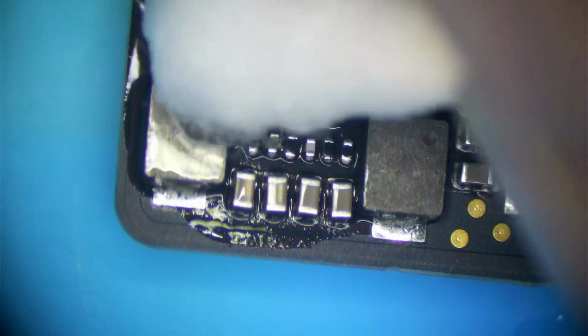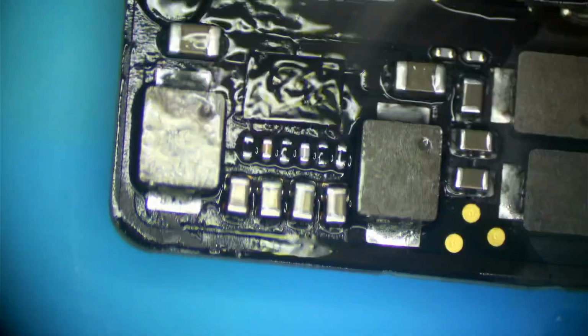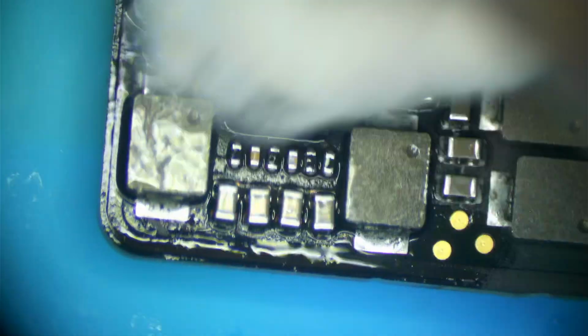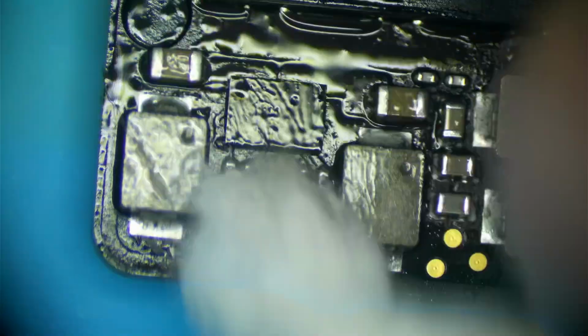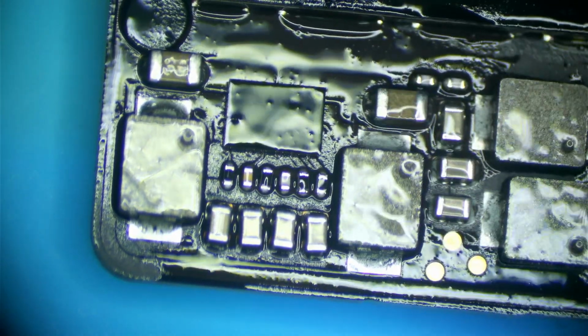As far as these go, I think what we're actually going to start doing is conformal coating these areas on devices that come in, because this is risky just leaving it. It is very concerning that Apple came up with this design. I have a dedicated video I need to edit on this, but yeah, this area can be really, really commonly hit with liquid, and not just liquid, just dust, and cause issues like that.